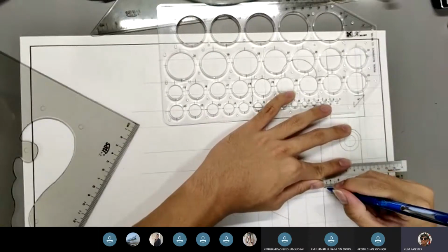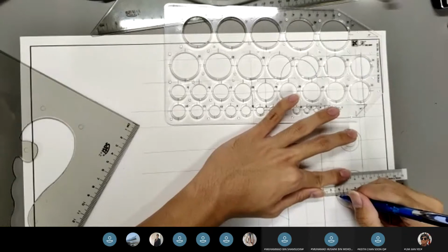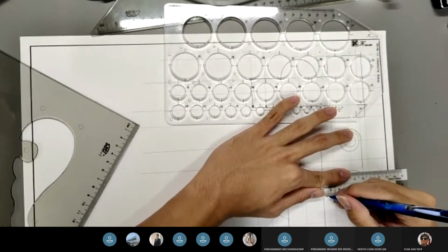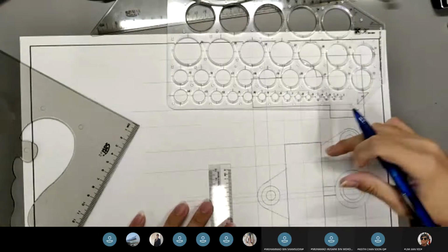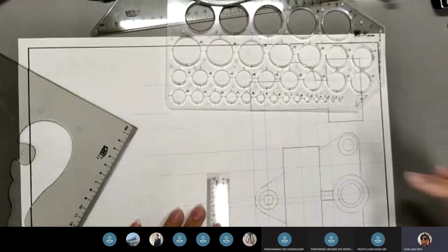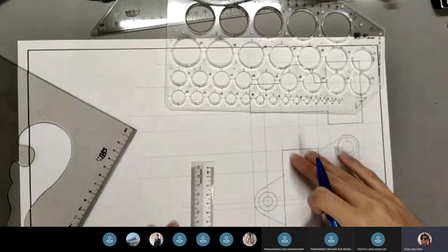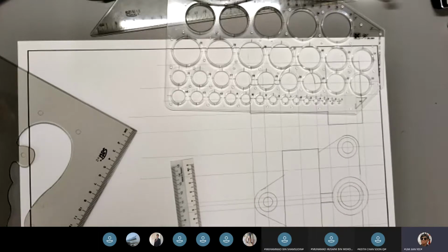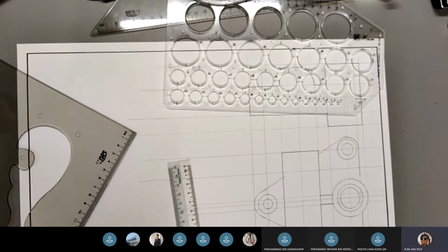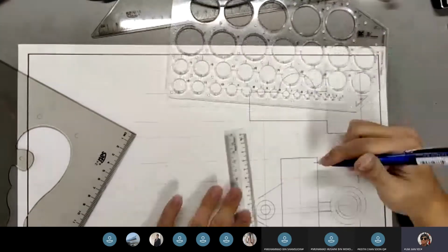This is the webbing. And let me fill in the features of this. So from the drawing, you can see it's a 28 diameter drill with a counterbore at diameter 32, with a depth of 24.